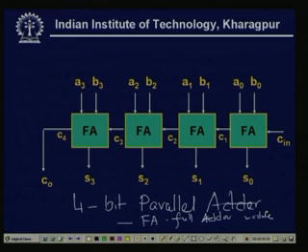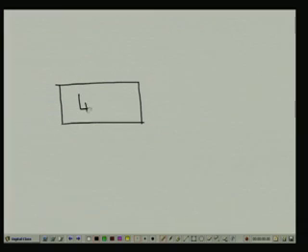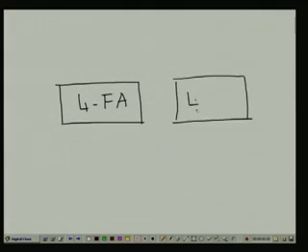Now, the second part: I will treat this as a module. So, this is a 4-bit adder, and from there we have to draw an 8-bit adder. Now, here I am writing 4FA, meaning a 4-bit full adder, and another 4FA we have taken, because for 8-bit we need two.